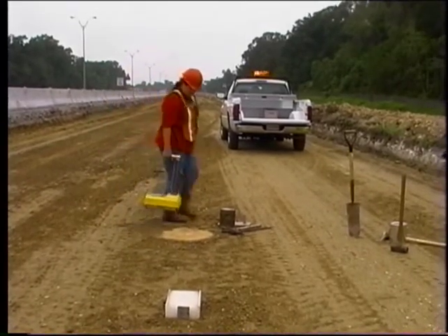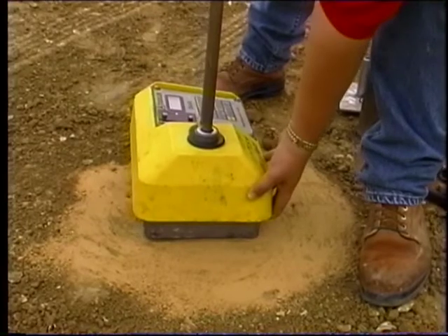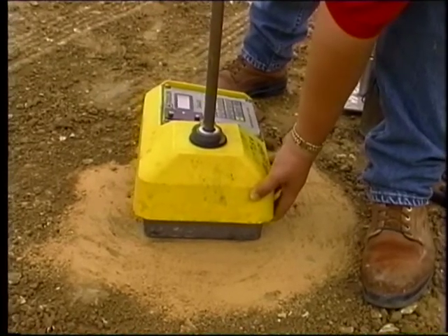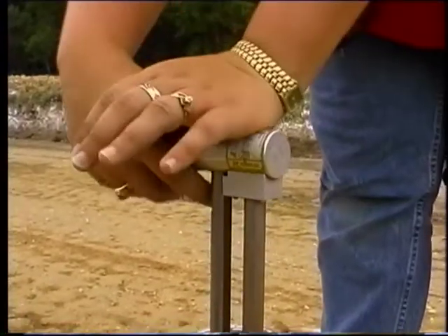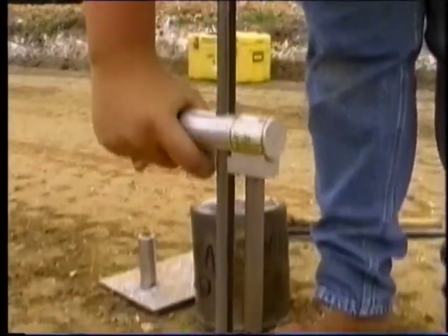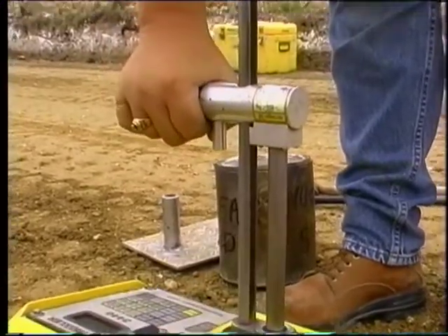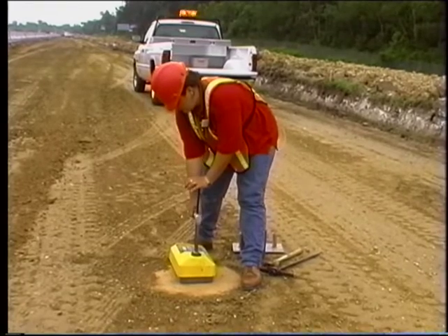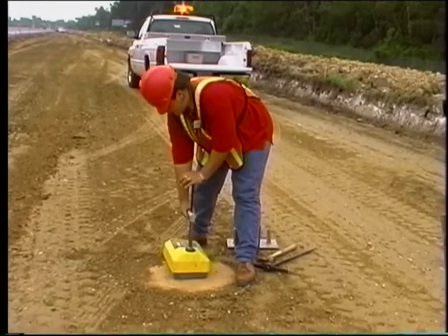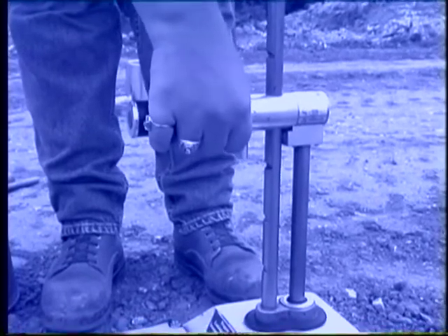Insert the source rod into the access hole using the handle and the trigger mechanism to the predetermined test depth. Release the trigger at the desired depth and listen for the positive click, indicating that the source rod is properly locked into position on the index rod. Press the top of the handle lightly to confirm positive source rod locking. Seat the nuclear device solidly by rotating it about the source rod using a back and forth rotational motion as demonstrated here.